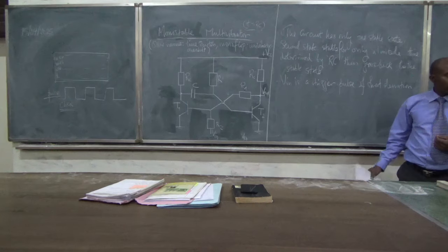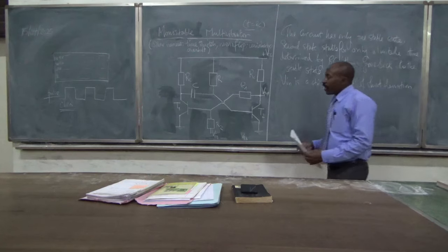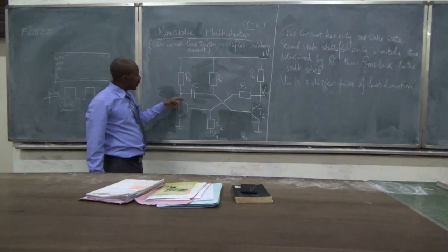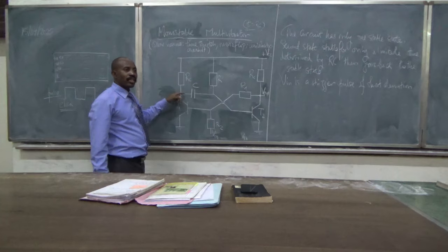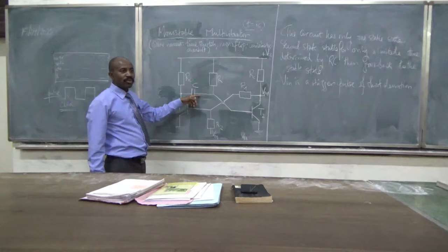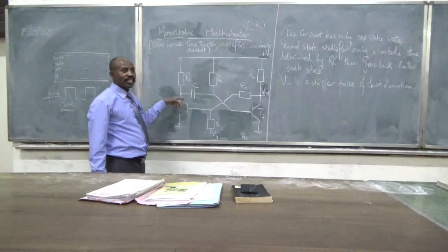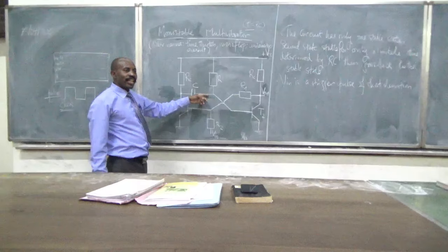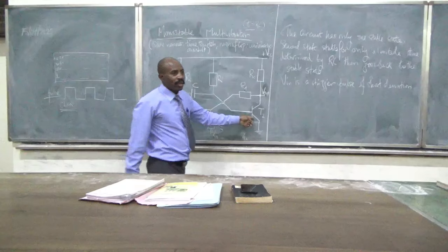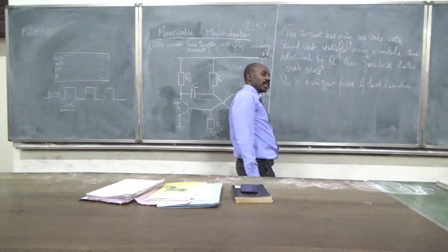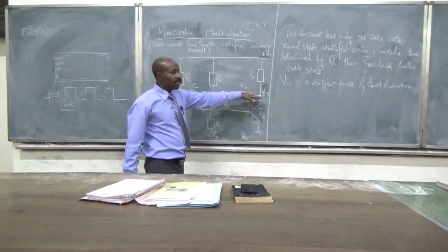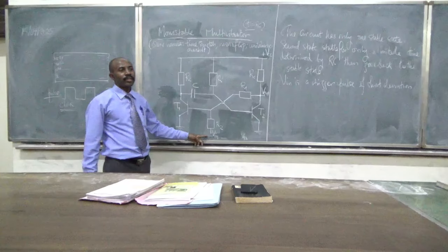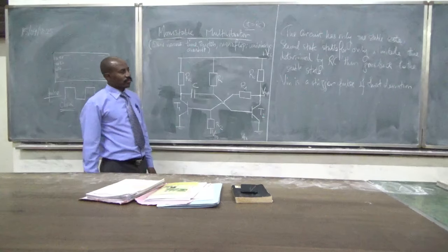So does this charge during the time when the transistor is open? When it's closed? When this transistor is blocking the current through here, it has a chance to go here. That's when it is able to charge. Now when it is conducting, everything goes here. And when it also charges and fills, that's when it is able to interact with this other transistor or bias this other transistor. And then you have the current blocked here, and then it comes this side. And then this one is just a pulse. So that's the trigger, the reverse bias?